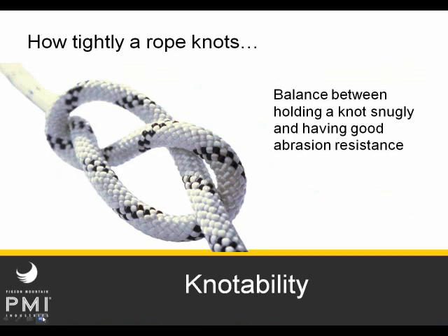Knotability is also a topic that I'd like to discuss. Knotability is a feature that's measured by most standards, and there is a minimum requirement in those standards to ensure that you don't end up with an entirely stiff rope. But most of us don't really think about it consciously, and we certainly don't specify it usually. Sometimes we subconsciously like the feel, referred to as the hand of a rope. A rope with a softer hand or greater knotability is usually preferred from an aesthetic point of view.